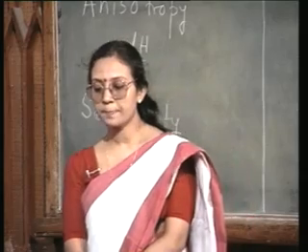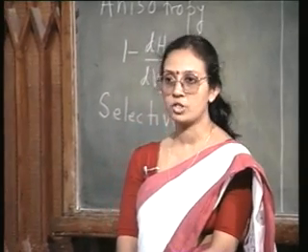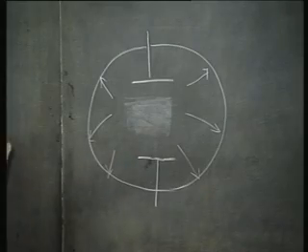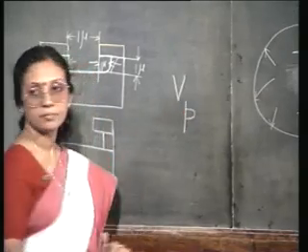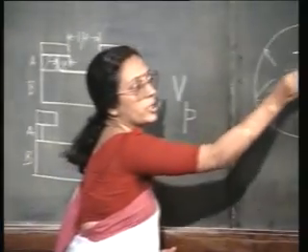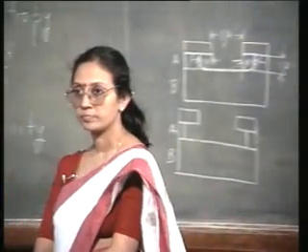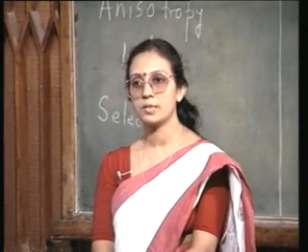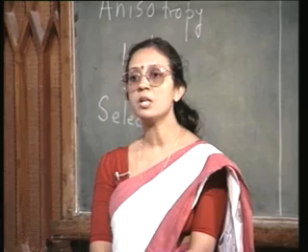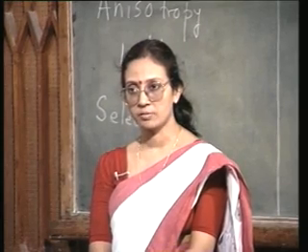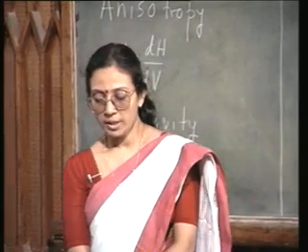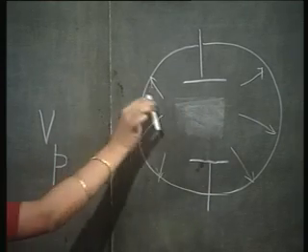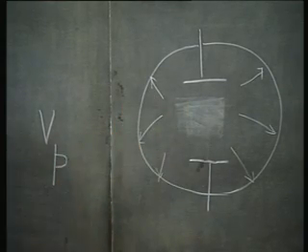So you see, the plasma potential, which is usually referred to as V with suffix P, the glow potential, is going to be positive with respect to the walls, because it is comprised mostly of the positively charged ions. Okay. So, I have a plasma potential Vp and I have electrons diffusing towards the wall.